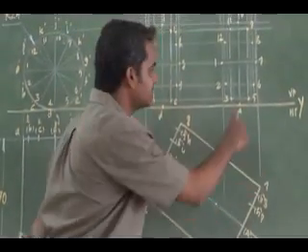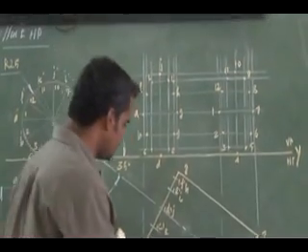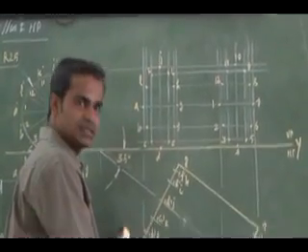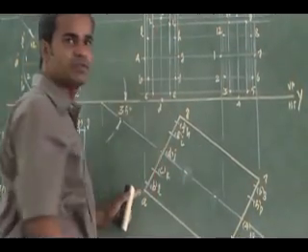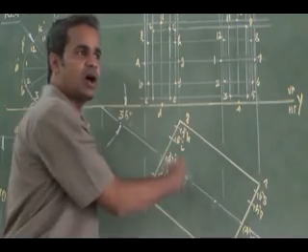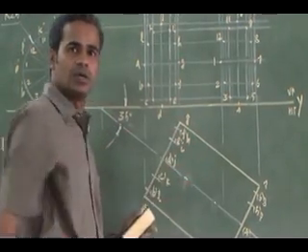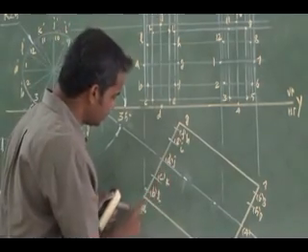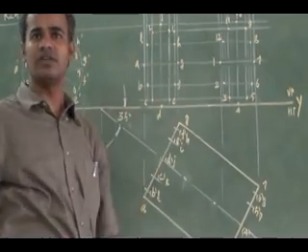That base point, I have to join as a continuous one. Similarly, the other base, the letter base, will be partially visible. Up to the axis, half will be visible, and above the axis, half will be hidden. Up to the axis half is nothing but A, B, N, C, K, D, J. So this half is visible, and the other half is hidden.